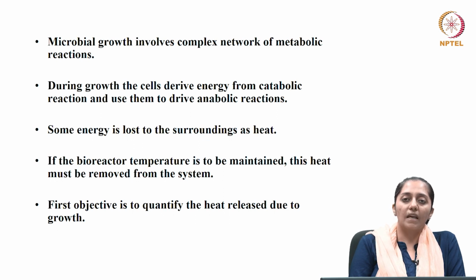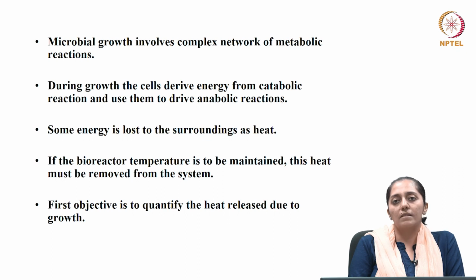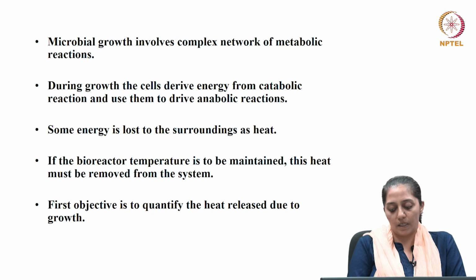Some of this energy during this process is lost to the surroundings as heat. Now, if the bioreactor temperature is to be maintained at an optimum value, then this heat must be removed from the system. So, the objective is first to quantify the heat released due to the growth of the biomass, which we may term the metabolic heat.